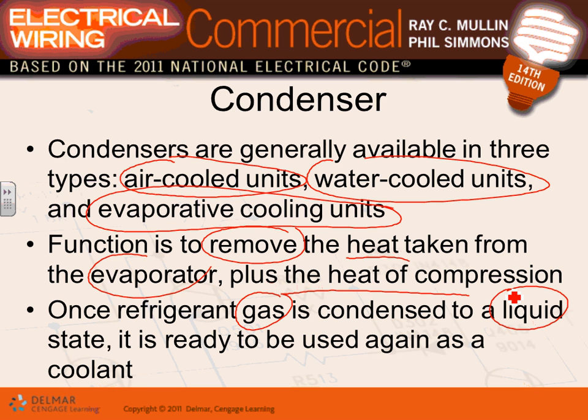One more time. You have liquid, it picks up the heat, turns into a gas, low pressure gas. Compress it into high pressure gas, then take it to the condenser. The condenser will pick the heat, throw it outside, and send it back as a liquid, and continue to do the process over and over.